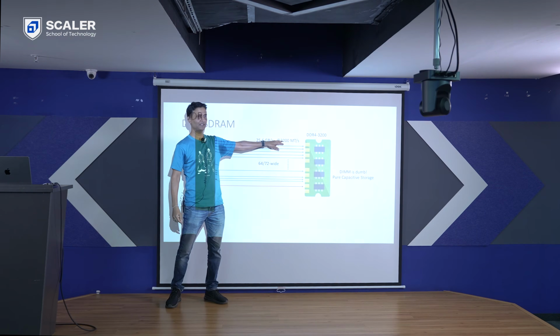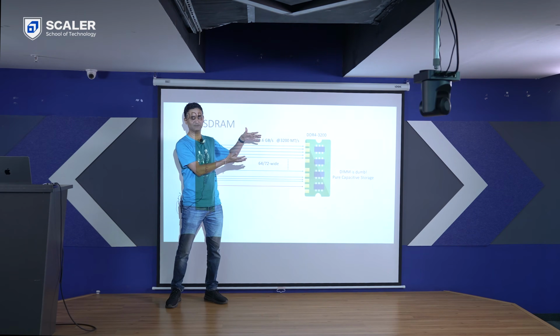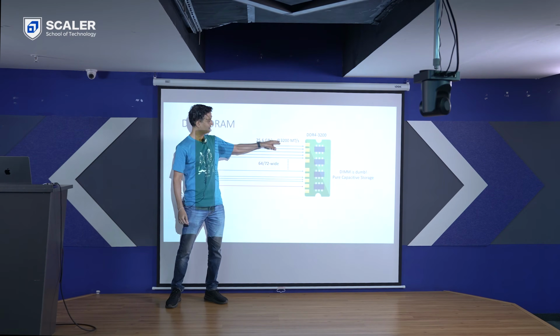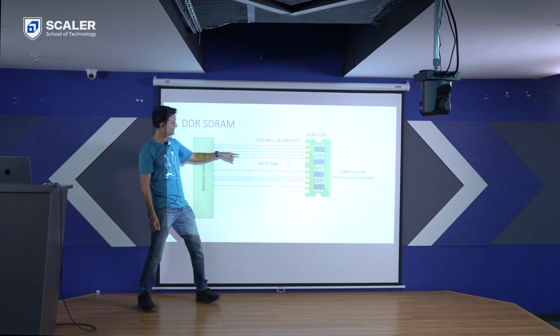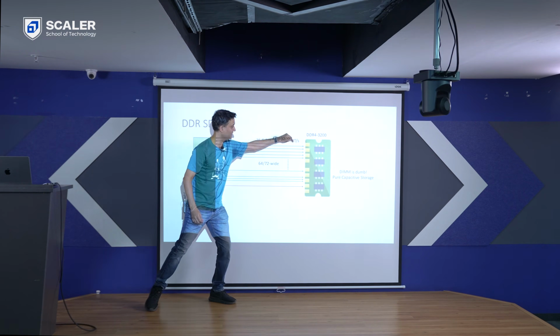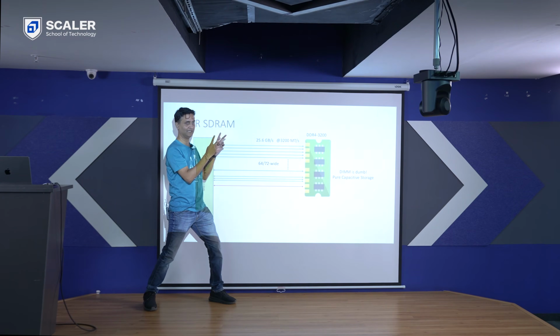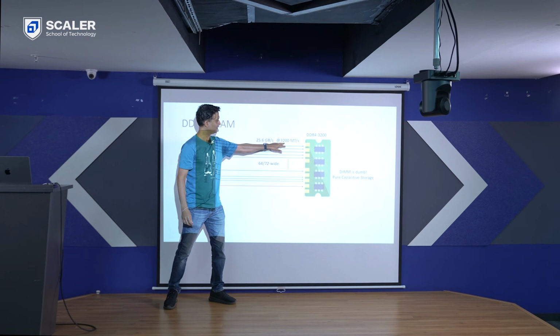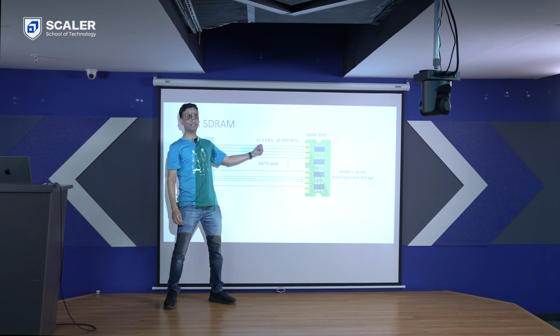So at 3200 million transfers per second, 64 bits wide, let's skip ECC for now, even with ECC only 64 bits of data are getting sent, right? So we've got 3200 million transfers happening in parallel. This is a parallel bus, okay? It's happening in lockstep. When there is a high, all of these things are getting sent, going low, another transfer. So double data pumping. So 3200 million transfers times 8 bytes. That gives us the bandwidth.